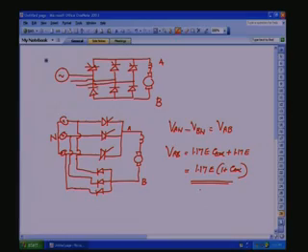Here we have introduced diodes so that we do not want the output voltage to go negative. If we do not want it to go negative, let us see whether this will happen. That means with the firing angle, we can have only 0 to positive value. Let us see a typical output voltage ripple for firing angle alpha equal to 60 and alpha equal to 90.